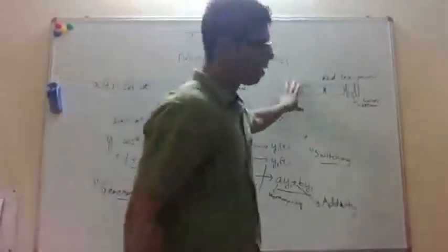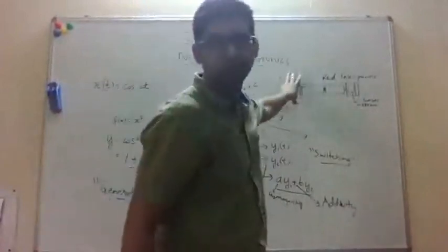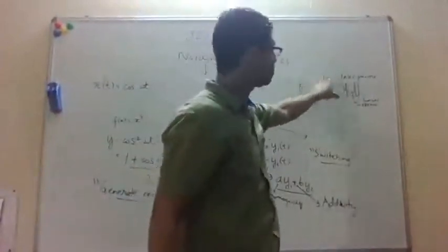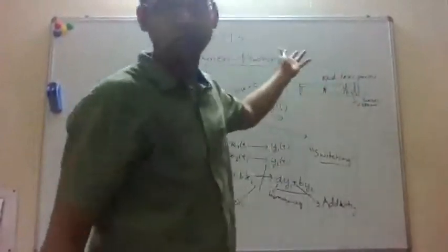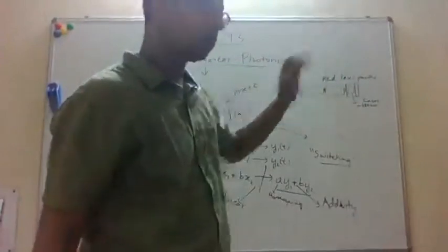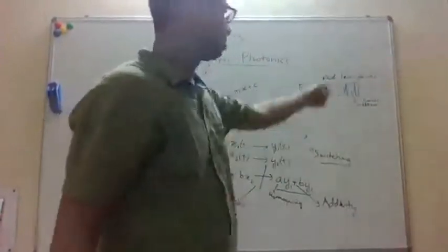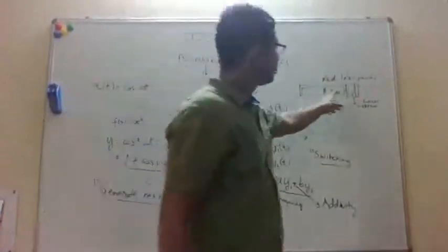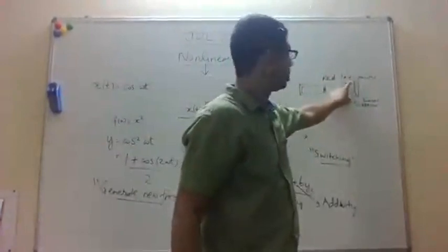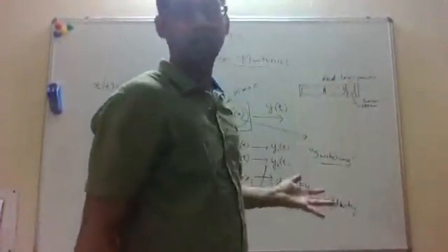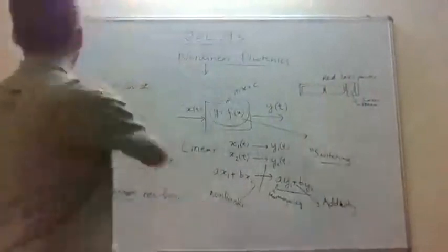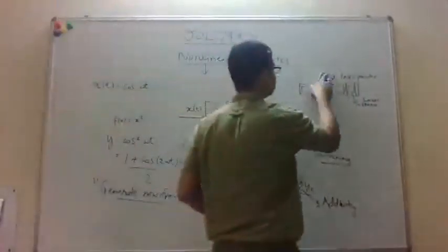On that point, I'm first going to the red laser pointer. The red laser pointer has just a semiconductor laser which directly produces red light. It has a band gap of the right value and emits light at a wavelength around, let's say, 680 nanometers, which gives you red. But for green, the problem is we don't have materials to make a good laser at green. In fact, it's very hard, and that's still an active area of research. So if you want green, you can't directly just make a laser.